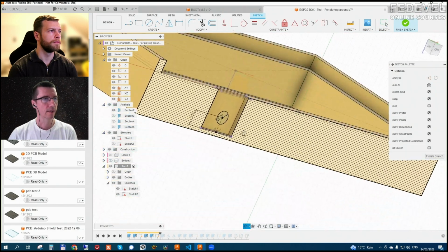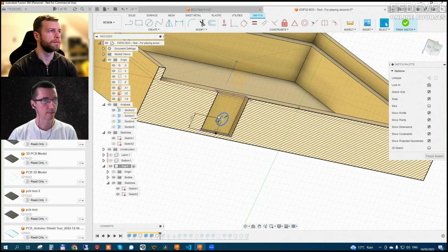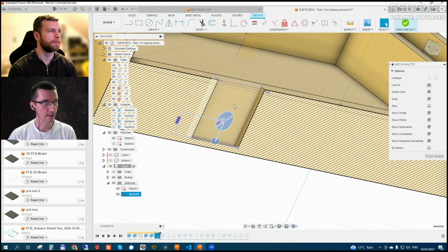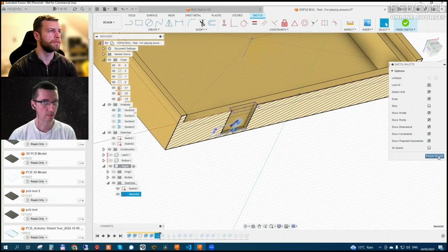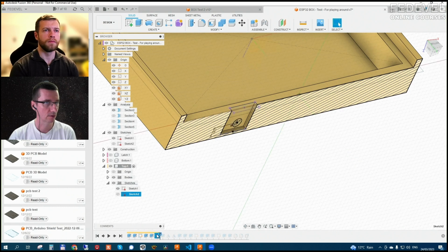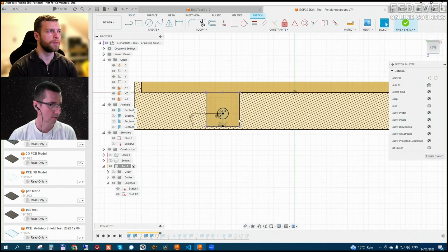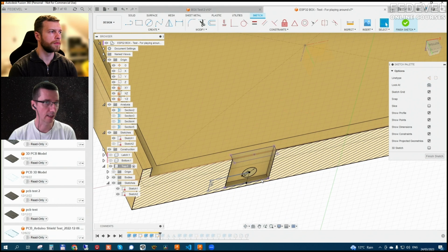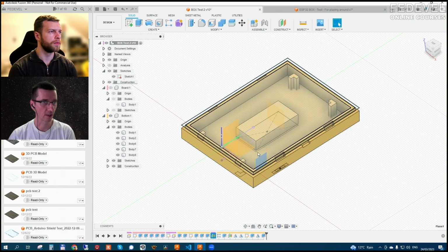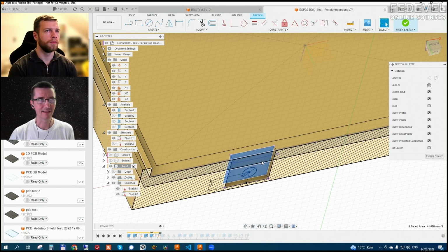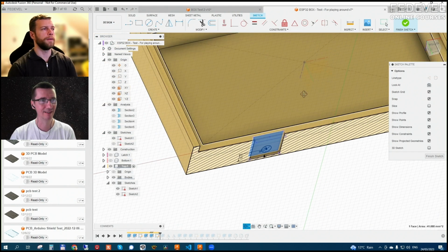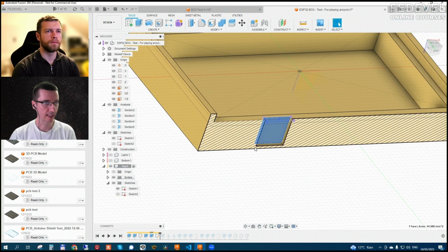So I created the hole, and as you can see, I created the sketch. Where is the sketch created? I don't know what is the reference plane for this sketch. Okay, I don't know where I created it, but in the new one, I'm using this offset plane for everything. That is what I'm planning, because as I said, you can create a sketch directly on these faces, but then sometimes it's tricky to reference them.